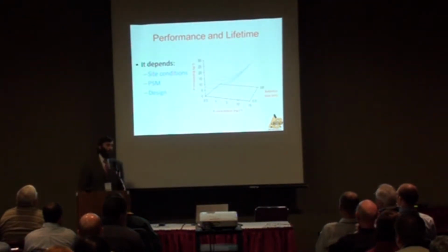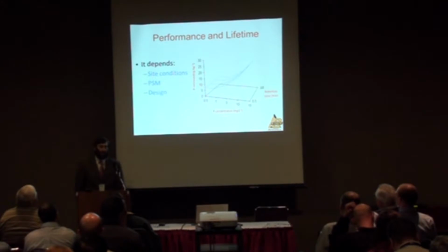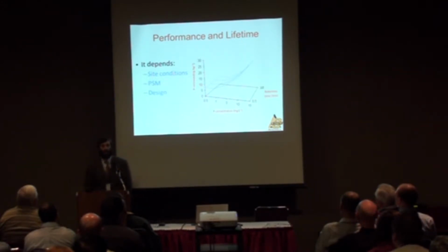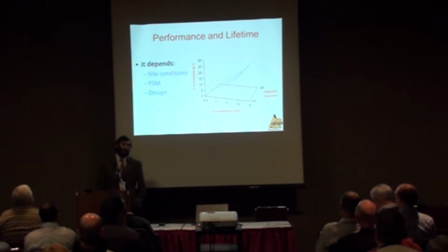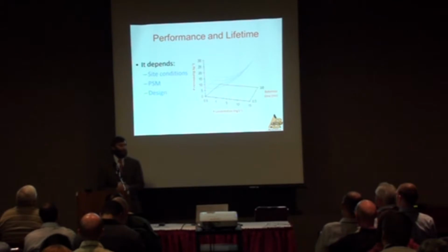So, how long do these things last? And how much phosphorus can they remove? The short answer to that is it really depends. It depends on a lot of things. It depends on the site conditions. What's the phosphorus concentration, typical dissolved concentrations at the site? What's the phosphorus sorption material, the PSM, that's being used? What are its characteristics? Some materials are better than others. And particularly, how is it designed?